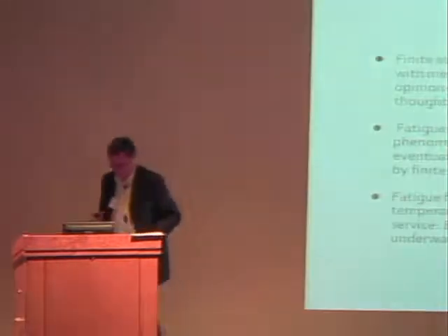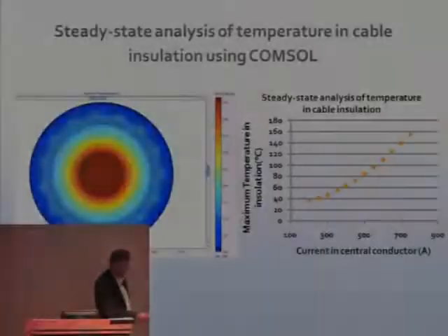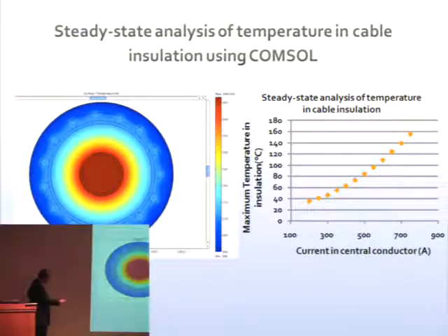Okay, a couple things. First of all, when you do a thermal calculation on a cable, most of the temperature drop is in the soil. So you can't fix the outer temperature at room temperature. But that makes things worse. No, the normal temperature drop across the insulation would be about 12 degrees. So the outer part of the wall of the insulation of the cable is not a whole lot lower than the conductor. Okay, well, if I make that surface hotter than the room temperature, then this is going to get even hotter.